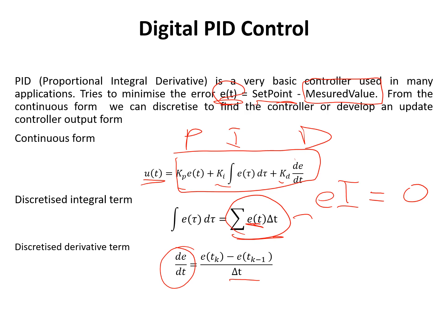Duty cycle, we typically get a different voltage by applying a duty cycle to our PWM signal, which is applied to our H bridge that does the speed control. And the output of our controller can be either duty cycle or the actual voltage.